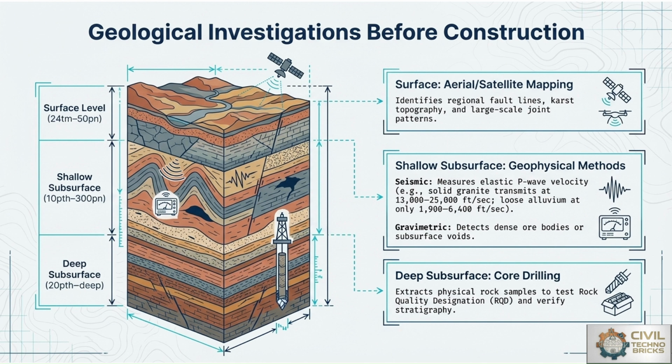The third one, the deep subsurface, is the actual core drilling, where external factors come into the picture, which extracts physical rock samples to test the rock quality designation and verify the stratigraphy. That deep investigation involves drilling, boreholes, and core logging. Here, the geological investigations provide information about quality of rock, groundwater conditions, and many more. These studies reduce uncertainty and improve engineering decision making.